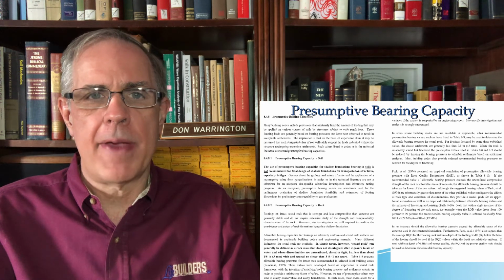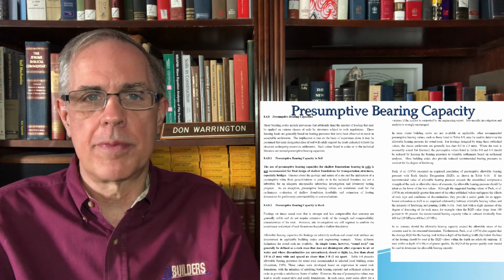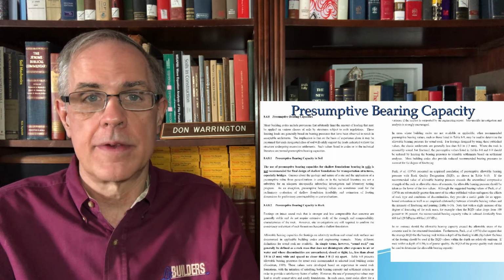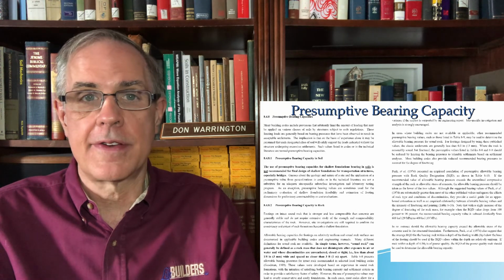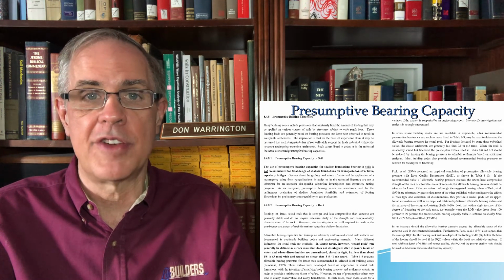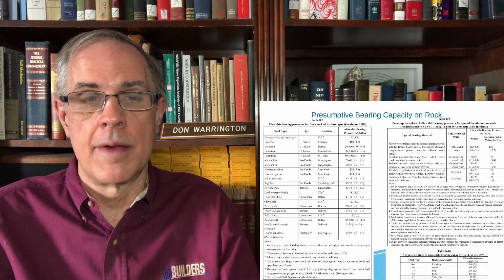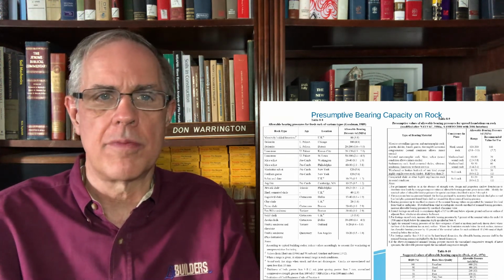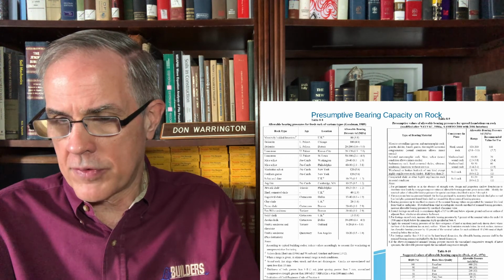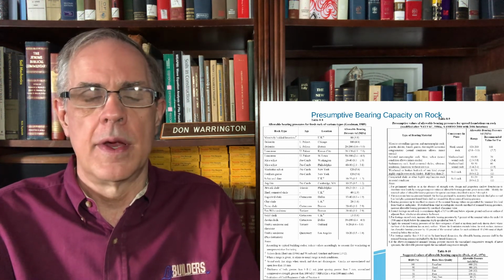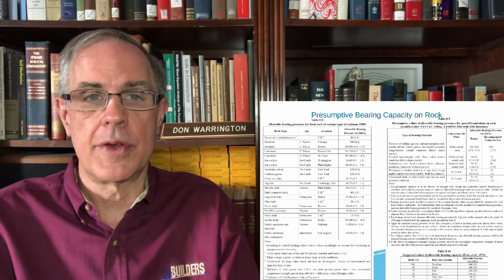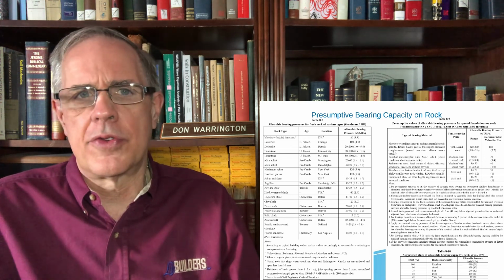We've gotten past that for the most part. You will see presumptive bearing capacities in codes, and if it's in a code, you need to deal with it. Sometimes it's very difficult to get an exception to a code, even when it makes engineering sense. But there's one place where we do use them more often, and that is with rock. Rock doesn't fail the same way. It fails a little differently than soils.